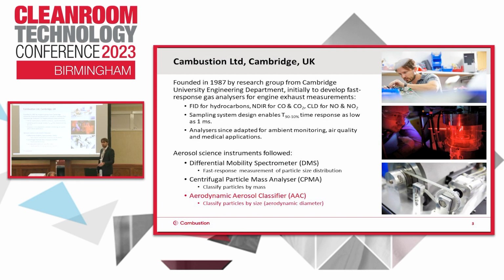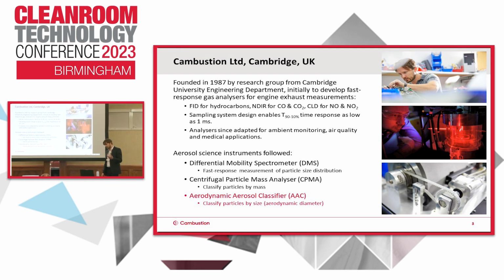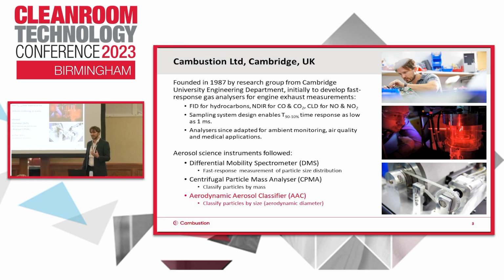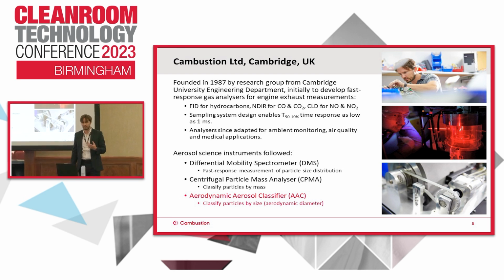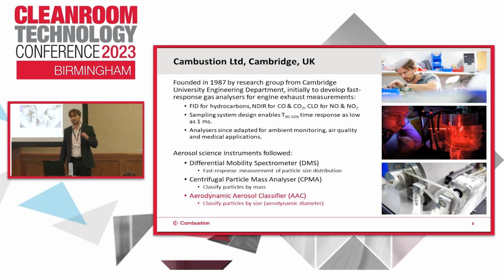So a little bit about the company I work for, Combustion. We were founded in 1987, spun out of the engineering department in Cambridge, initially to develop fast response gas analyzers for combustion exhaust measurements. Those were using industry standard techniques: flame ionization detection for hydrocarbons, non-dispersive infrared for CO and CO2, and chemiluminescence detection for NO and NO2.